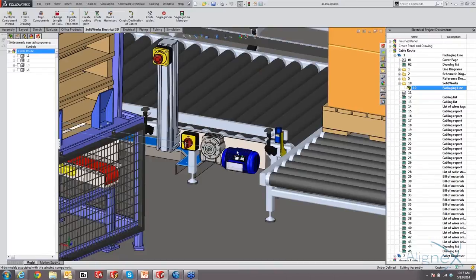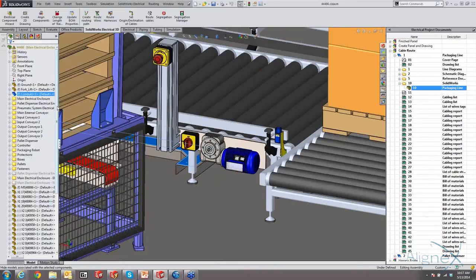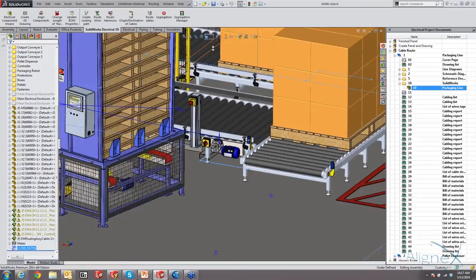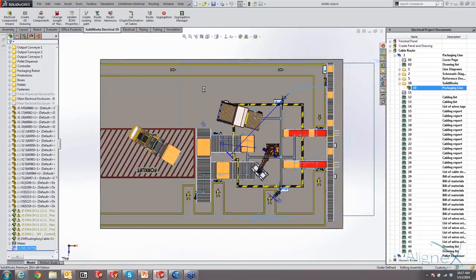So we're going to actually tell the electrical using, again, that sketch. There's a sketch right here called EW_path. And let's go to a top view. You can see what that looks like. So this is the 3D sketch coming from the motor over here through on the floor over to our panel. So this is the route that we're going to be taking.